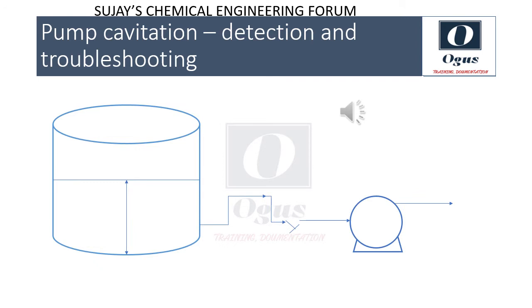To eliminate cavitation, follow these steps. 1. Reduce pressure drop in the pipeline by cleaning possible blockages in the suction line. 2. Reduce number of bends. 3. Check all the valves are open fully. 4. Ensure sufficient liquid level in the tank. 5. Ensure the pump is being employed to pump a liquid of same density, composition, and boiling point as designed.